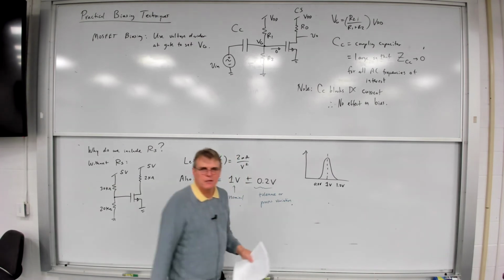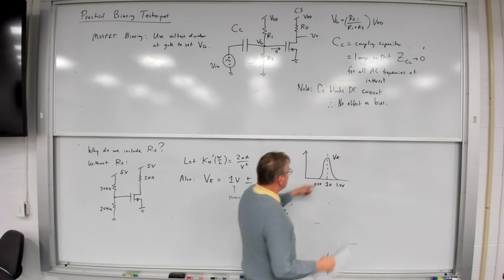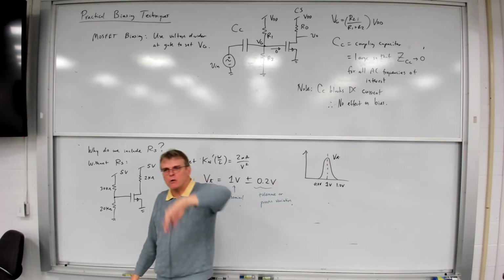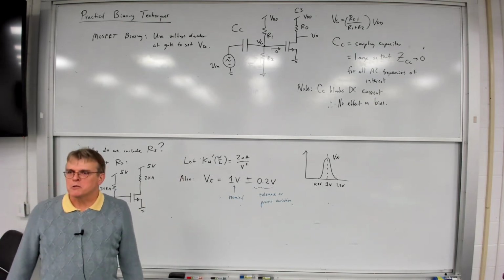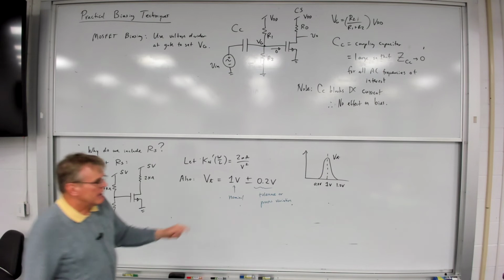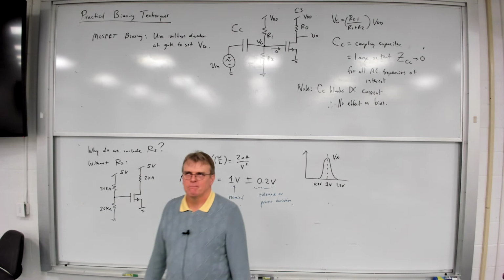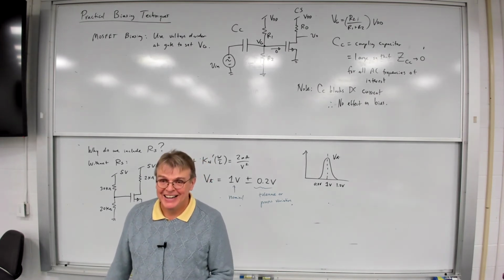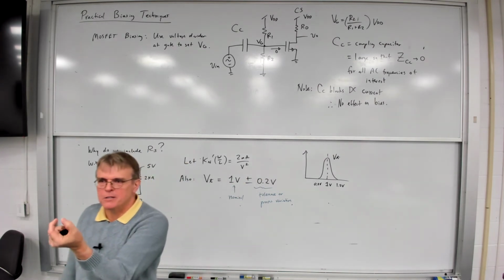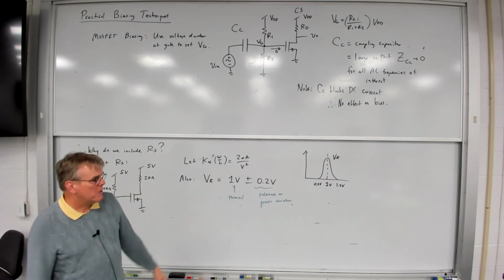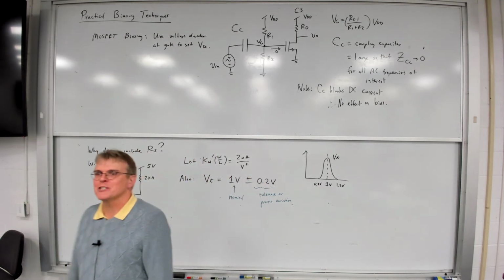So this is what this means when we're looking at this for VT: you're going to typically have a Gaussian tolerance description, a probabilistic description. Every component you will ever purchase will have this. If you want to tighten up that tolerance and make it narrower, what do you have to do? Spend money. It's going to cost you more. If you want tighter, better tolerances, you have to pay for it. So components with big tolerances are cheap. Components with very tight tolerances are expensive.